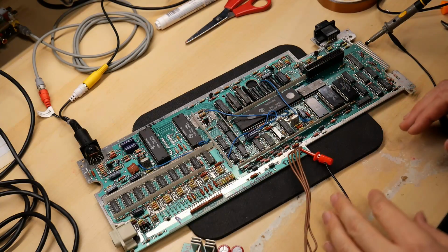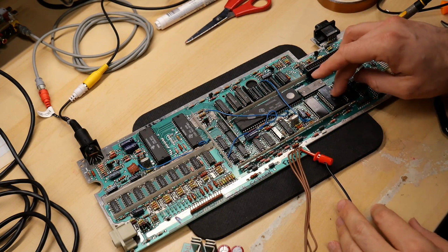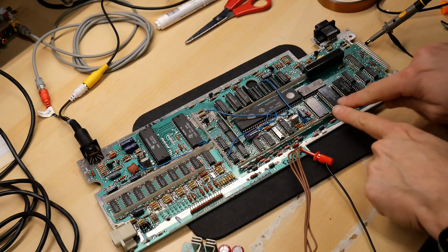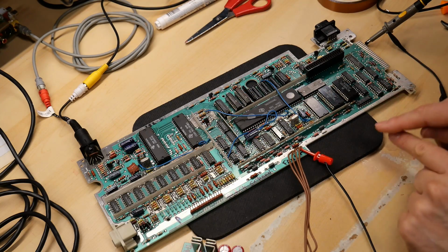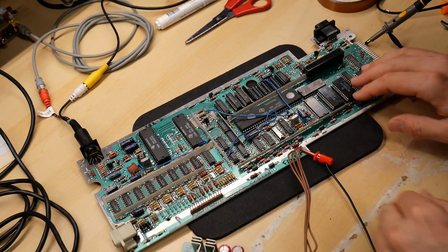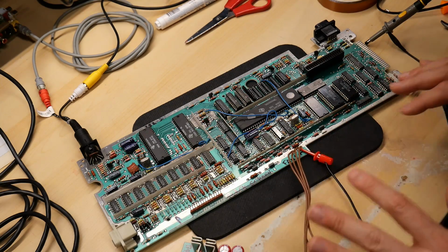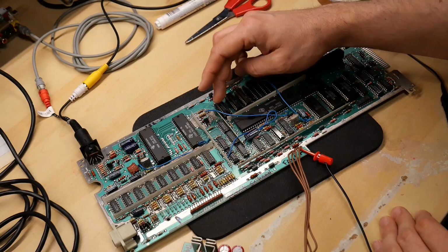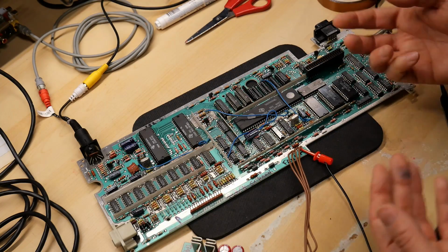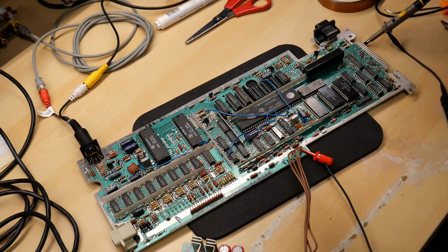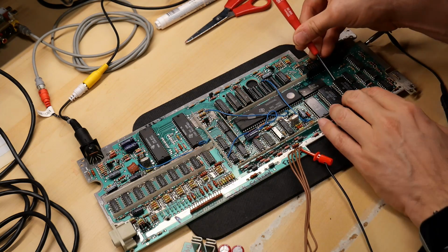So there's a couple things to try. First, I could try swapping the two RAM chips around and see if those bad lines follow the chips or stay in the existing sockets. That's a good test, because if we switch these two chips and nothing seemingly changes, then I know the problem lies elsewhere, either with one of these three ICs here, or it could be the ROM chips, which I didn't pull out. You know, I don't know why I didn't socket those. I should have done those at the same time.